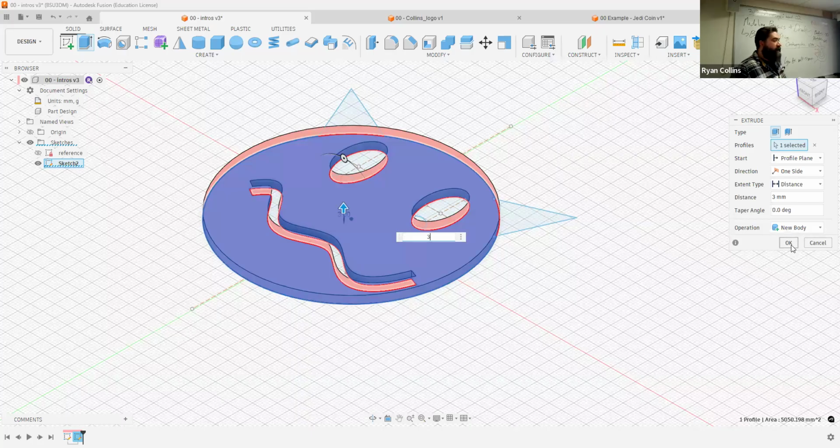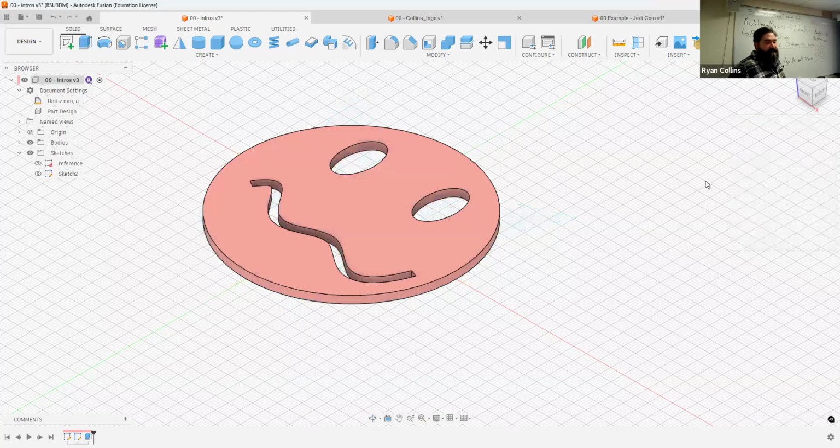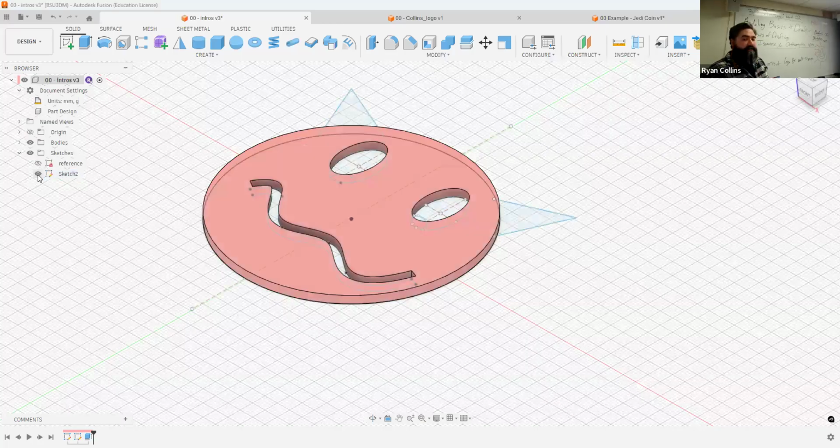Cool. Okay. Hit okay. My sketches are gone. It's okay. It just automatically hides the first time. So just there, hooray, you've made an extrude. One single extrude. Now, what Fusion does, regardless of how complex your sketch is, it assumes, yep, you're done with that now, right? So if you go back over and unhide the little eyeball symbol, it brings your sketch back up. There you go.